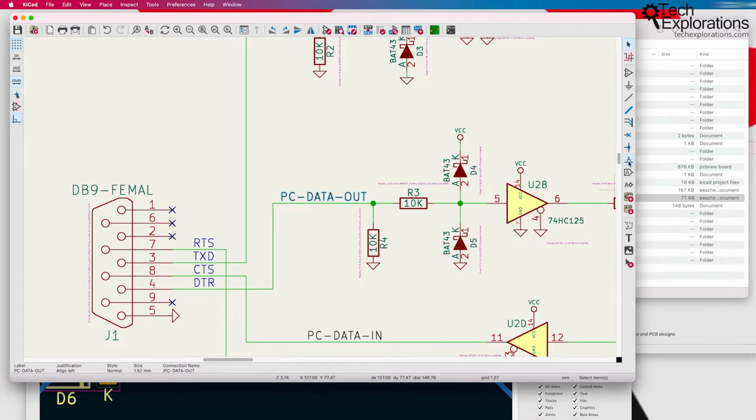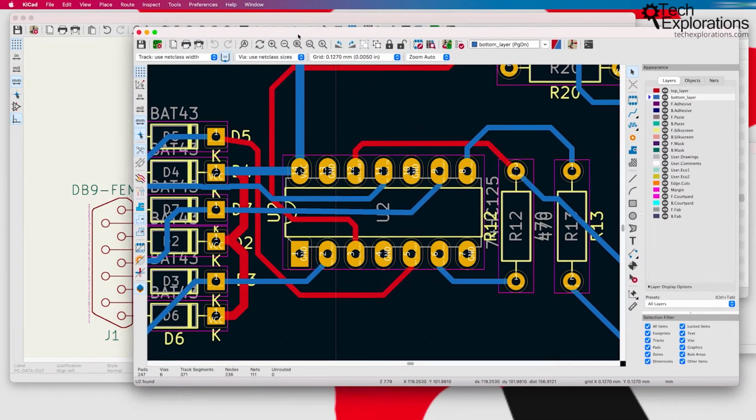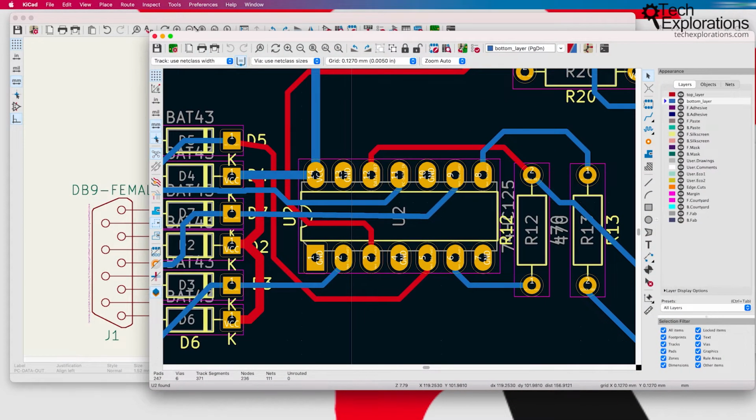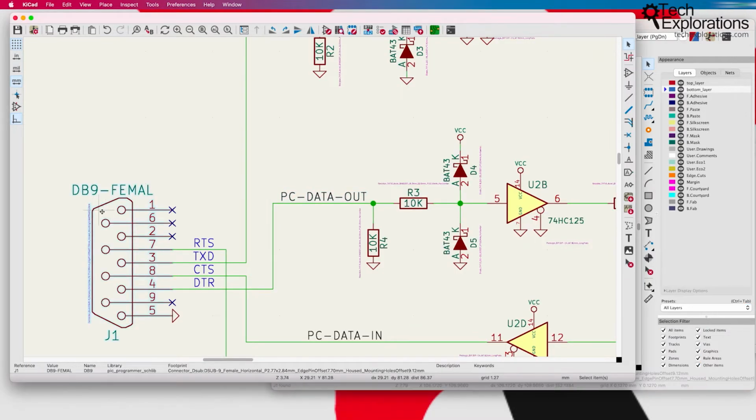It's a label that we can pick up from the tool bar on the right. And that label, we assign it to a wire. And now this wire has got a name. And very often it is very useful to have a name in wires. It makes it easy to see them, for example, in the PCB layout right here. So let's check this out. In the schematic, I'm going to click on this component.